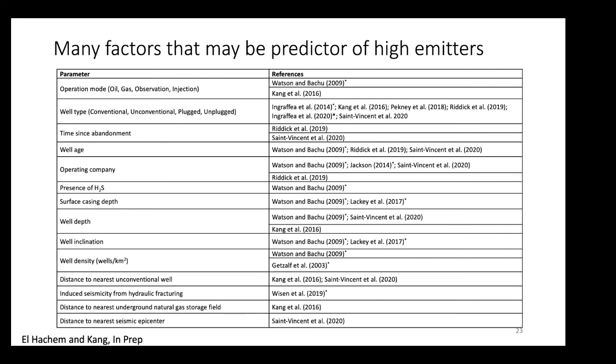I want to continue on this slide. I see the factors that you are considering to monitor for wells. Do you also consider the completion of the wells, the integrity of cementing, and the gas that may escape and leak from behind the casing? In the picture that I saw, there are no pressure sensors or pressure gauges to know how much gas is behind the casing. Even inside the wells, there is no pressure gauge. They are very old, so the integrity of the wells most probably has deteriorated over the years. So there is a high probability of gas escaping behind the casing.